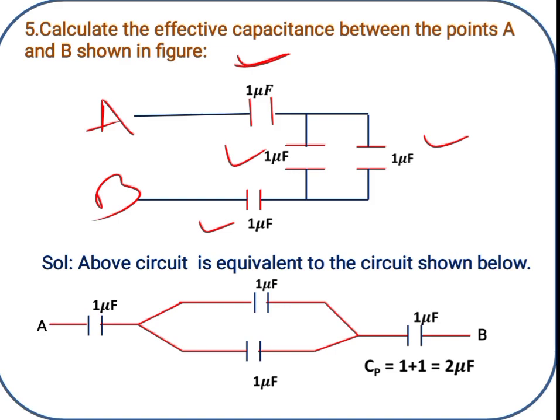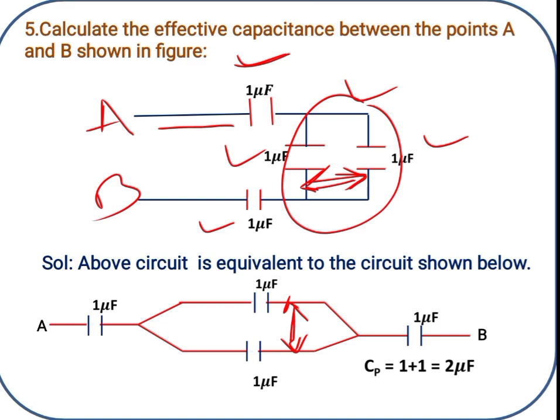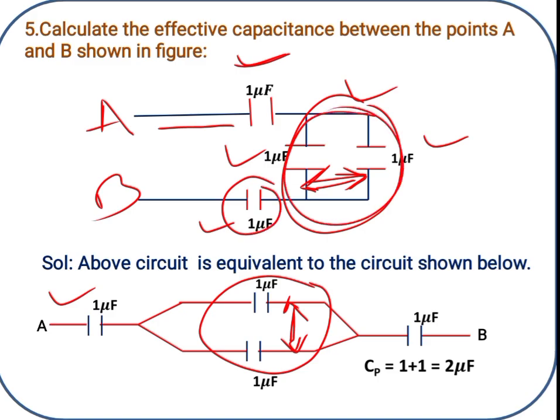Before this we have to first simplify the circuit diagram. You just carefully see, both these two are in parallel. Are they not parallel? So I redrew the same diagram in this way. This is in series with this combination, this is in series with this combination, this is in series with this combination. So I redrew it here.